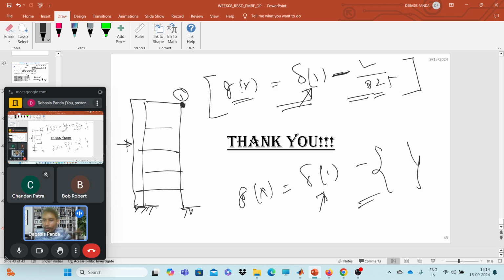And my wind code will say this will be the permissible limit. So permissible limits will be your capacity, and this actual model will be your demand. So g(x) will be capacity minus demand. You can easily form your limit state from capacity and demand. Capacity is like on which parameter you are looking at. You are looking at the displacement, deflection, stiffnesses, whatever you are looking at, you can check it.